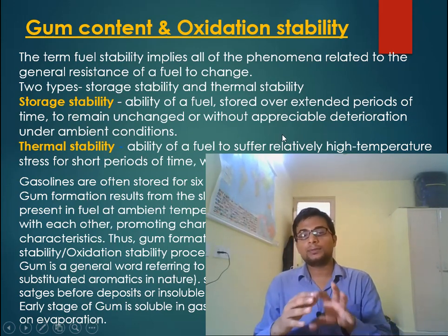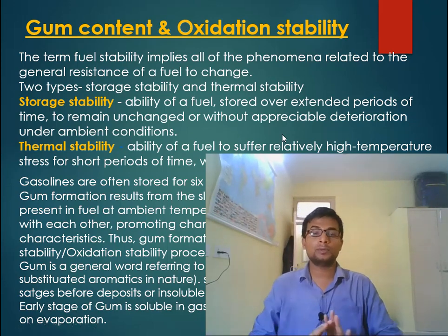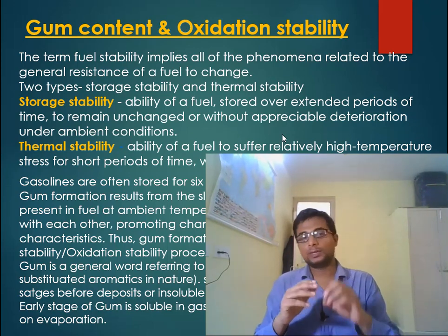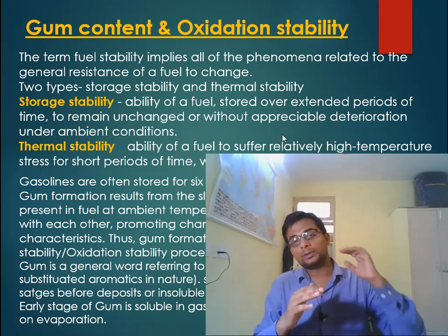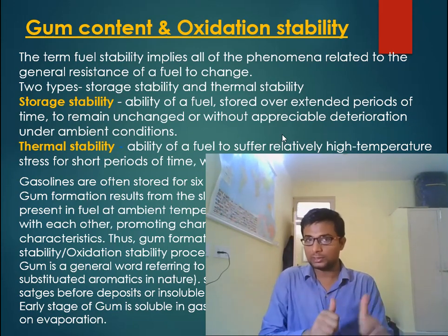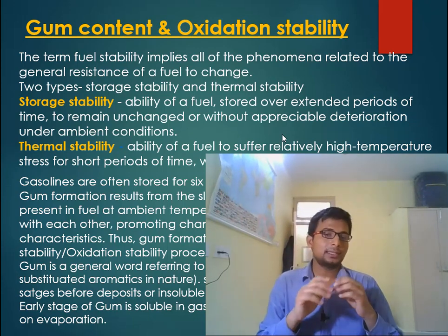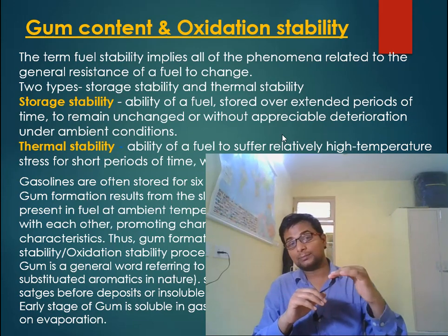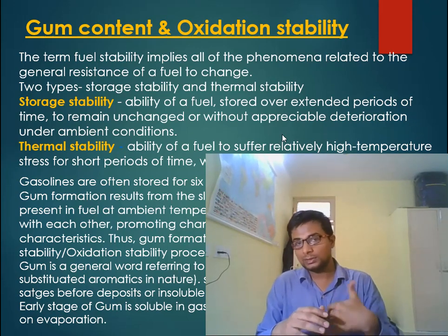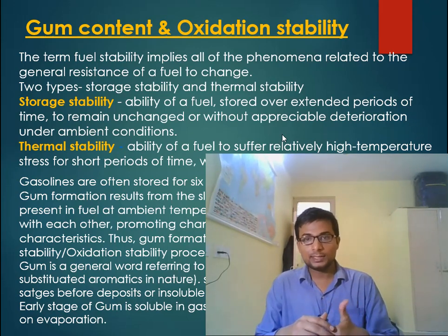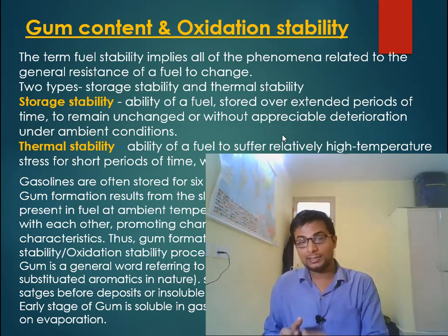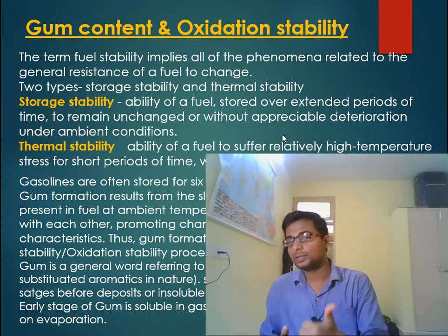Storage stability is the ability of a fuel to remain stored for an extended period of time without any appreciable deterioration under ambient conditions. If a fuel has very good storage stability, you may store it for a very extended period of time and it will remain as if it was just manufactured. Thermal stability is the ability of a fuel to withstand relatively high temperature stress for a short period of time. If you keep petrol at a very high temperature, it will undergo deterioration. But if you put it at a very high temperature for a very short time, and it resists any change during that time, then it has very good thermal stability.